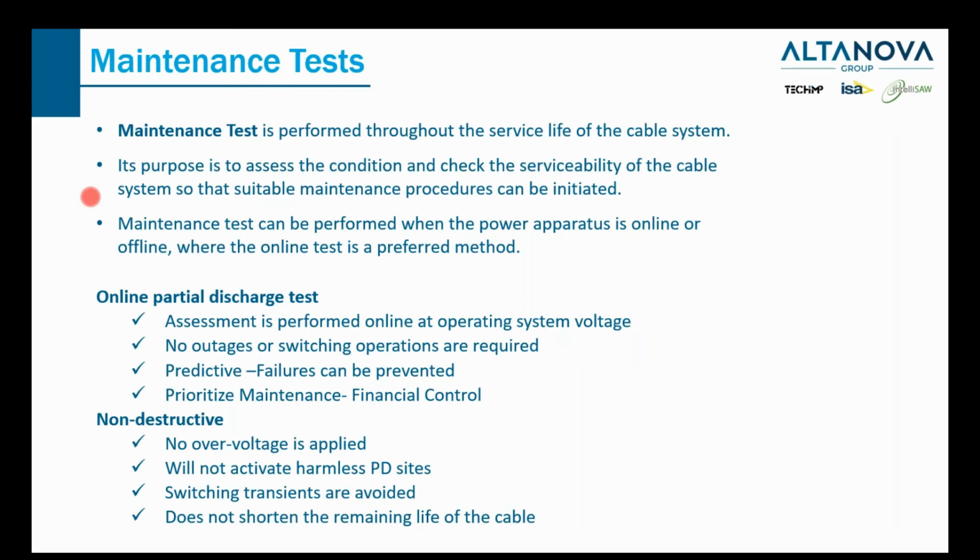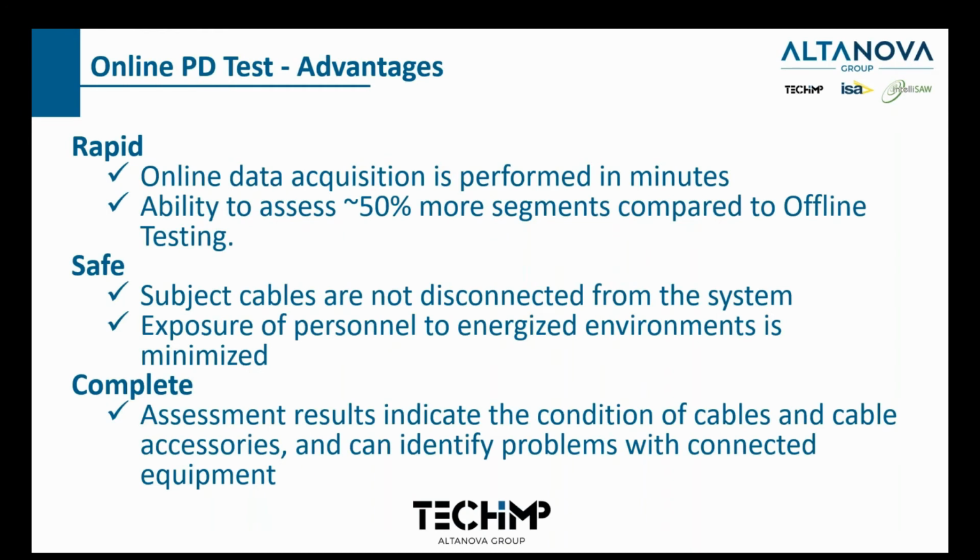And also, since there's no switching, and the switching transient could be 3 or even 5 times higher than the operating voltage, we can also avoid the switching transient. So that's the big advantage of online testing. It's really non-destructive.